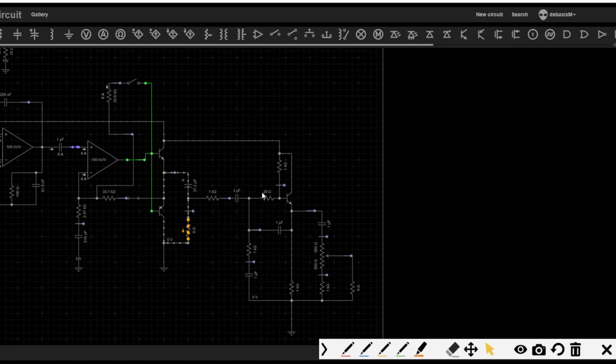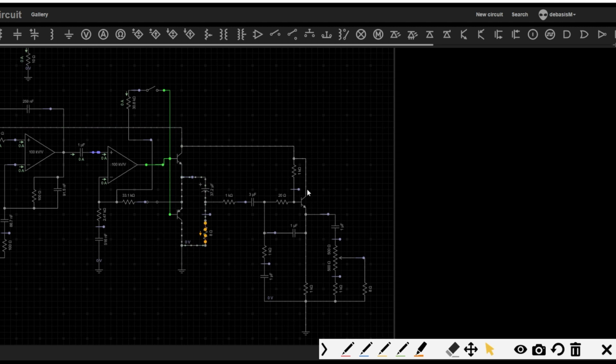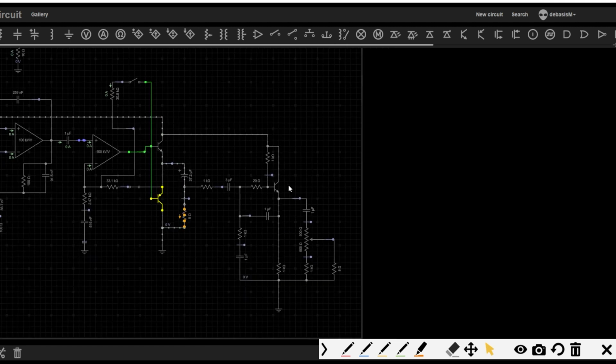This part is actually again a low pass filter. It removes all the high frequency signal because you would like to operate your bass for the low frequency region. Effectively these resistors and capacitors are creating a low pass filter. So that voltage is getting filtered again and goes to this NPN transistor. Some amplification is going on here, and of course some filtering is happening, and from the emitter you have, in parallel, your bass adjustment knob. From the bass adjustment knob you have this resistor, the bass coil, the bass speaker resistance, kind of an 8 ohm speaker.